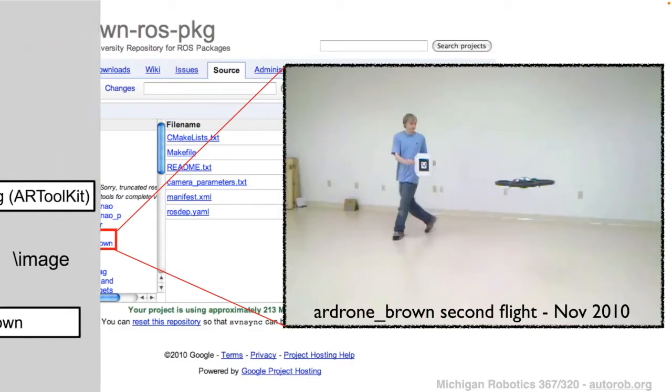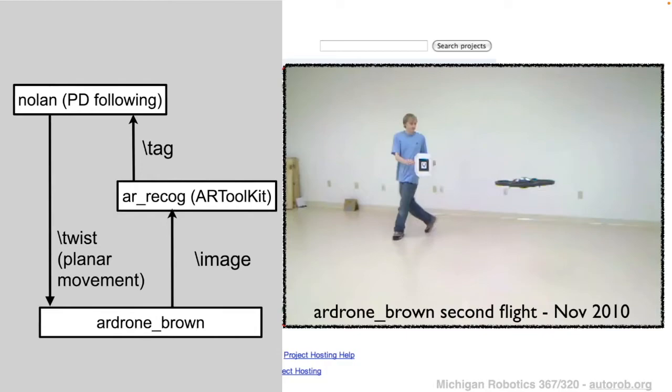In this particular case, the setup for our ROS workspace would be 3 individual ROS nodes. First we'd have one ROS node for the robot itself. We'd have a second ROS node which is running recognition for the AR tag. Just to show, in this image here, this is the AR tag. And then we would have a third ROS node running the controller for the drone to calculate its intended